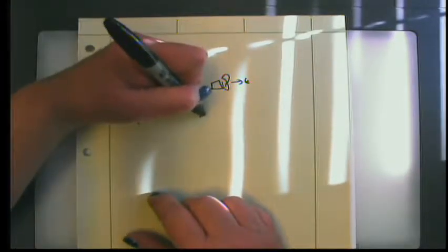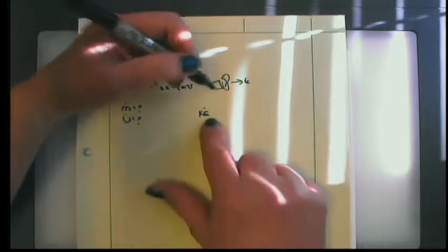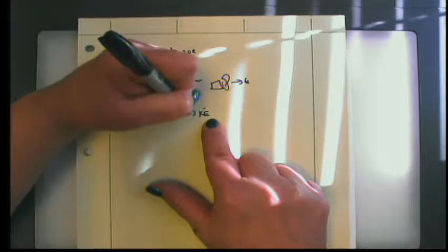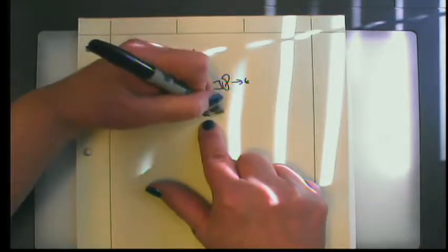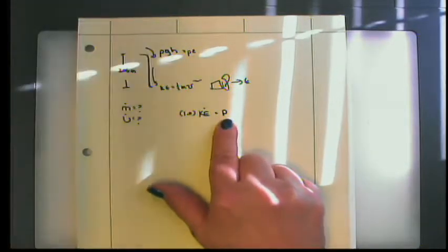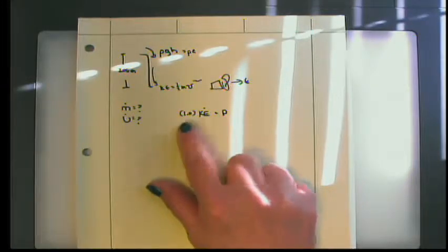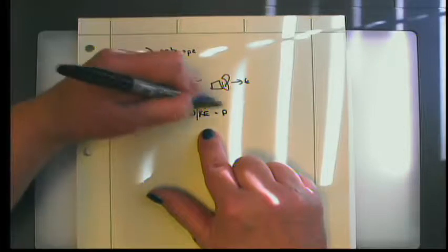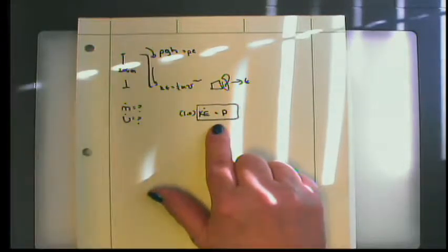It doesn't really specify. But at what rate must water pass through the hydraulic turbines at this dam to produce 100 megawatts of power? So what we're really looking at is the same thing. We want KE dot times this efficiency, which here is 1.0, equal to the electric power. But we're saying that it's 100% efficient. So in this case, KE dot is equal to power.